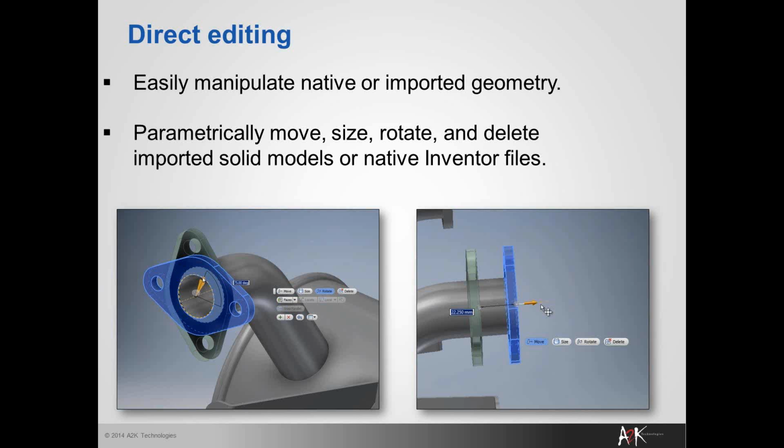So what the direct editing allows us to do is make those changes, and we can basically stack as many changes or variations to our model inside of one feature that we're not necessarily committing to. We can go back later and decide whether that editing process needs to be included in our workflow or not, or whether we scrap that design and start again. So as a concept stage, making changes, exploring design options, it's extremely quick and extremely powerful on both imported models and native Inventor files.